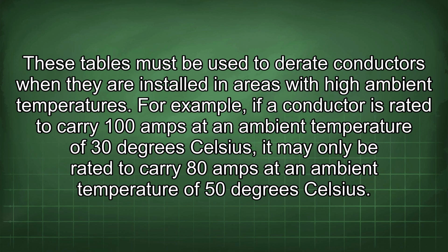For example, if a conductor is rated to carry 100 amps at an ambient temperature of 30 degrees Celsius, it may only be rated to carry 80 amps at an ambient temperature of 50 degrees Celsius.